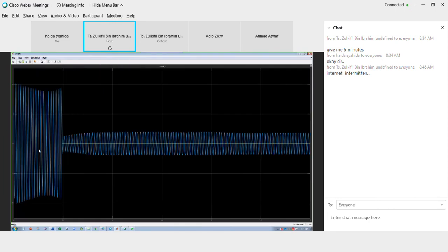You have two different configurations. For the starting current it is the same at this area, you look at the current value and you can compare. After the machine runs at almost synchronous speed, the yellow one has turn equal to 0.